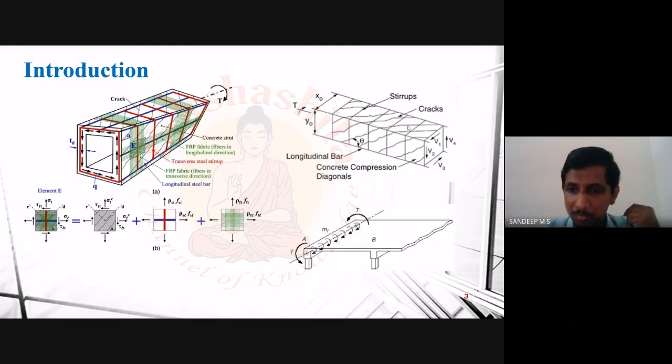You must be able to observe like that, and please understand that the cracks due to torsion will always be inclined at approximately 45 degrees, and cracks will be formed on all the sides of your beam. Now the next question is how to prevent this. These cracks are formed when you have force acting in the perpendicular direction. Tensile force must be applied in the perpendicular direction so that the weak section will fail and get opened. That is what we call a crack.